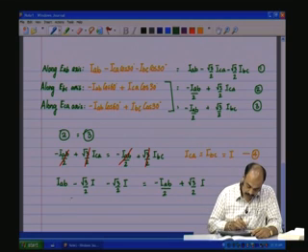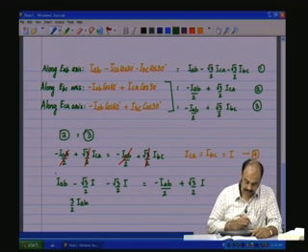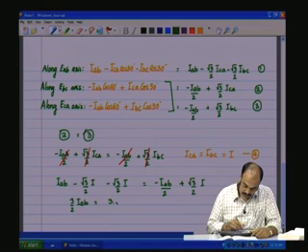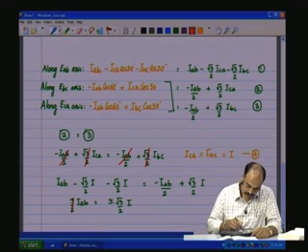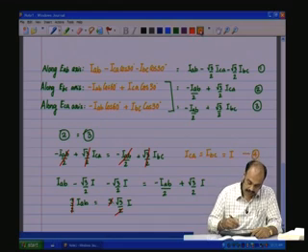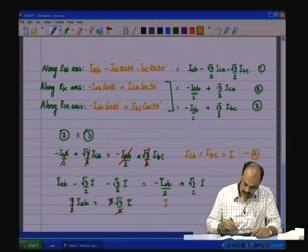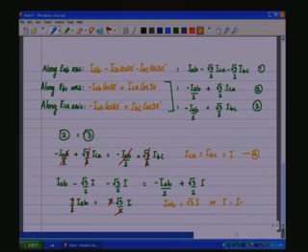So, now taking I_AB onto the left hand side, 3 by 2 I_AB, and taking these onto the right hand side, you have 3 times root 3 by 2 into I. So, this leads to the following nice relation: I_AB is equal to root 3 I, or I should be equal to I_AB by root 3.